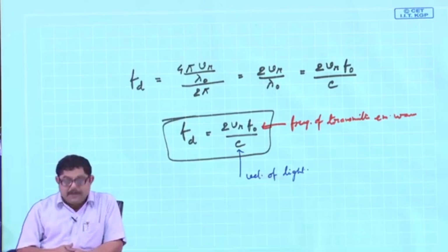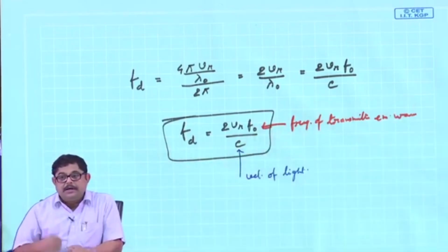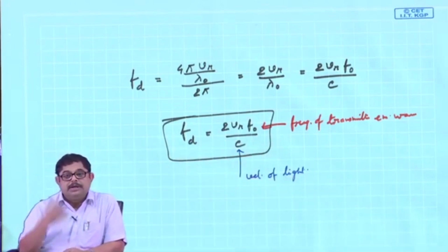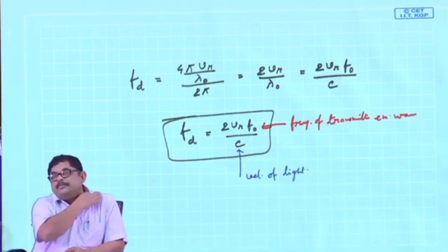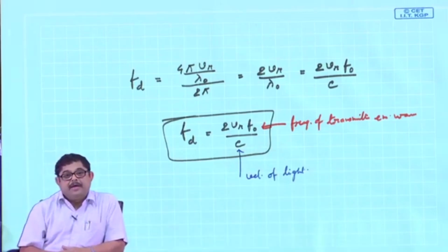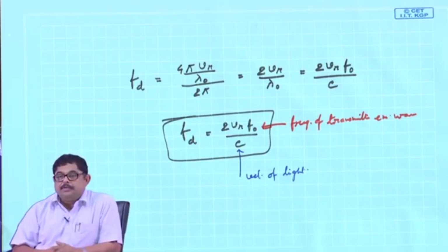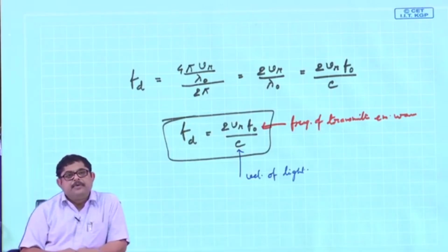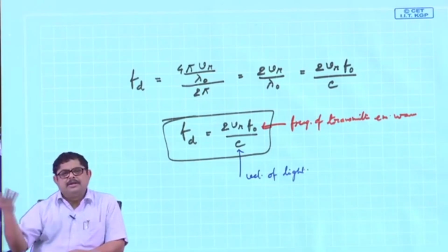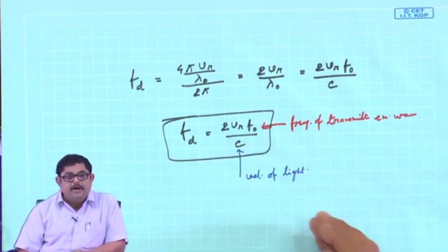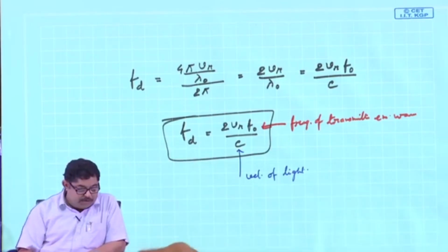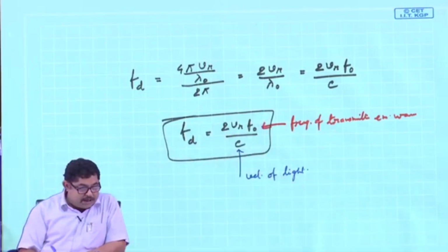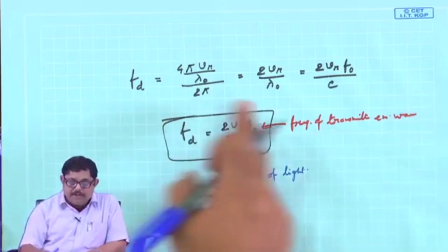So, from that you can calculate that suppose I am sending a 10 gigahertz signal, and let us say the velocity is the aircraft speed. Fighter aircraft speeds are given in Mach. 1 Mach means 1 speed of sound. Speed of sound you can take 330 meters per second, or even 300, 320, 330, something. So, you can easily find out how much Doppler shift will be there, that will be given in the exercise. And remember one thing, that when I am saying the velocity,